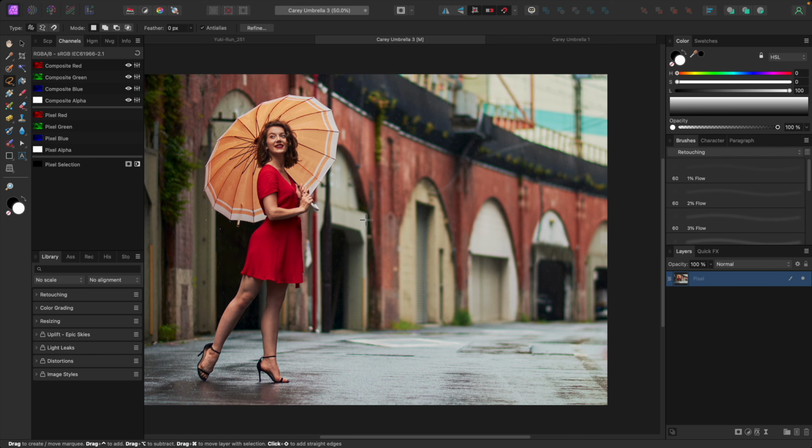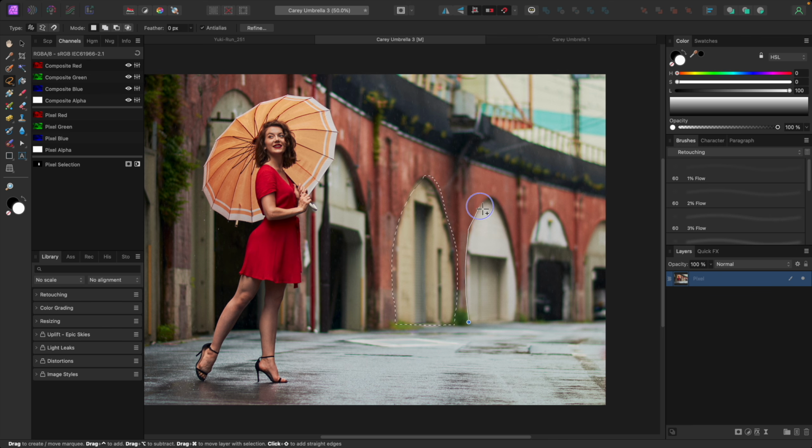Also, while you are in the new mode, let's go ahead and deselect this here. You can use modifier keys to change your mode without having to click up here at the top. If I make this selection like before and want to add to it, I can press Control on my Mac, and that will present a plus sign, or if I press Option, it will present a minus sign. So by holding down Control, I can go into add mode, and if I hold down Option, I can go into subtract mode. That is very useful and definitely speeds up your workflow a bit.